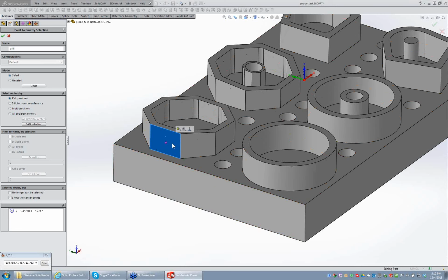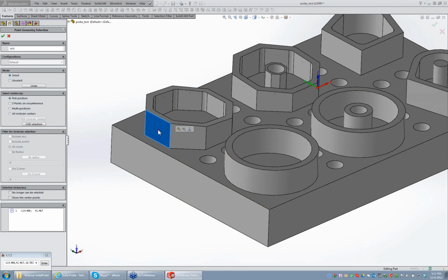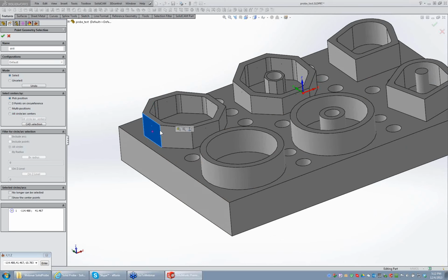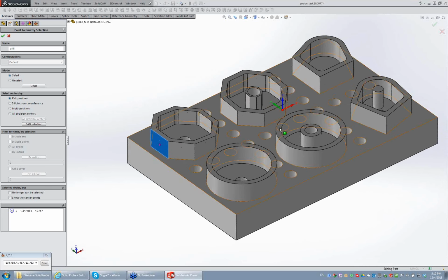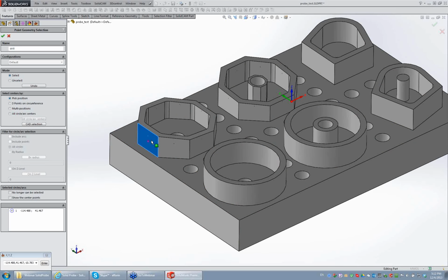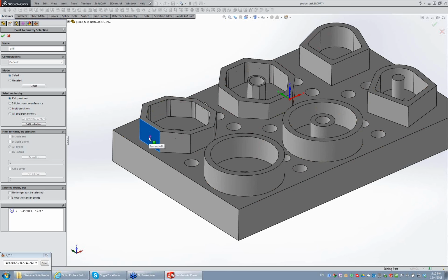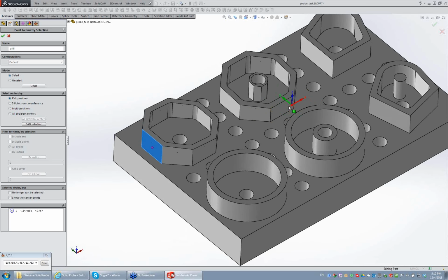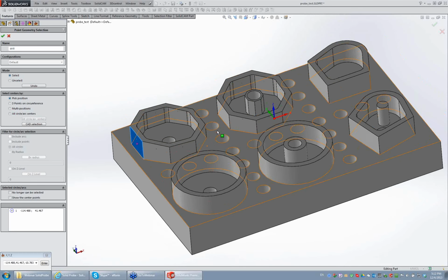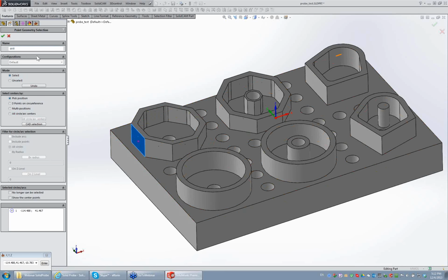For example, I want to touch with the probe this wall and to define the home, where it is defined in the coordinate system manager. I define it in the middle of the part. So if I touch this wall here, the probe cycle will tell the controller your home is at a specific distance that we measure from this part. So I define a point,